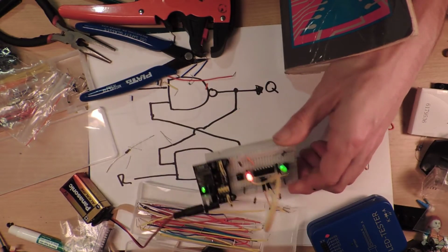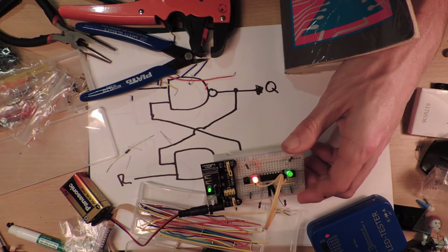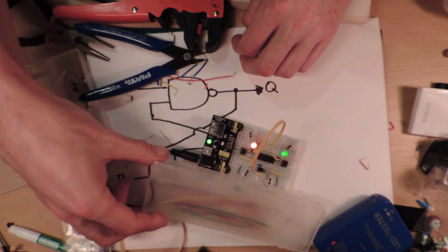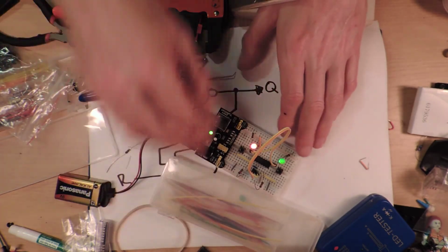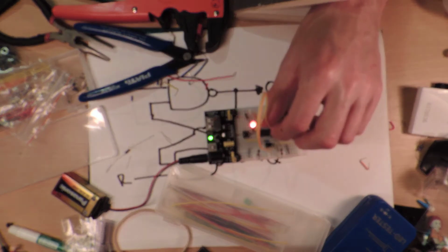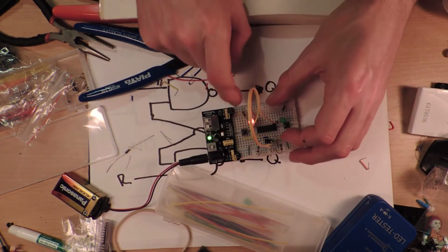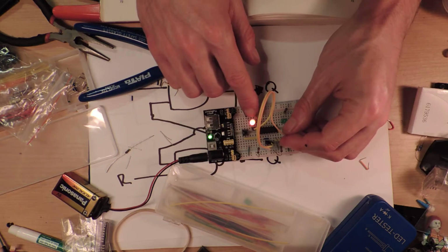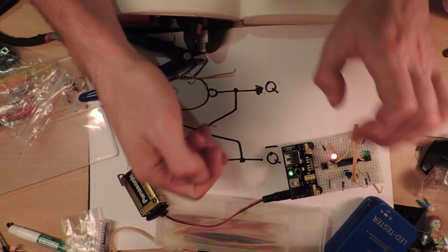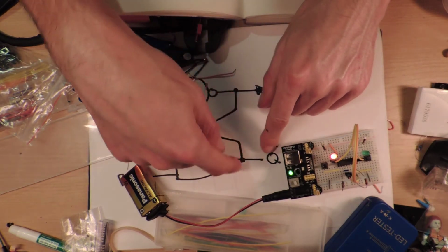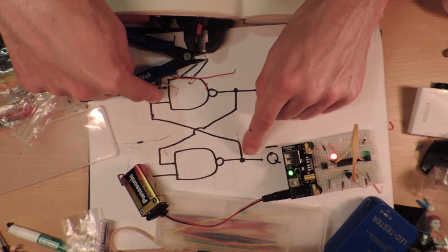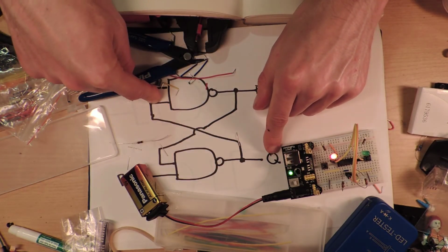oh, it might be the same kind of problem because they're not buffered. Oh, I didn't think about that. I should have, because that was the whole point of the 4049 conundrums. So what I might have to do is check the LEDs, because they're probably interfering with the circuit here. This is going to create a voltage divider through the LED when this is a positive voltage, so you might not get the voltage you're expecting, though I think you would, wouldn't you?